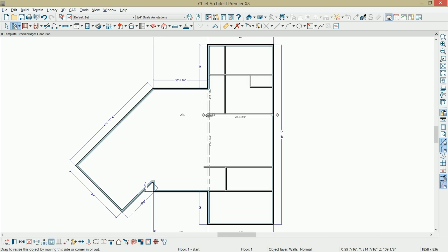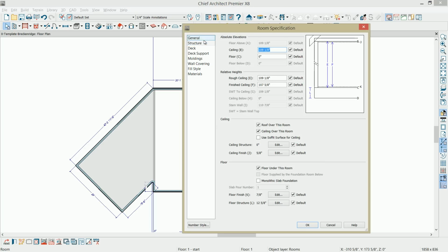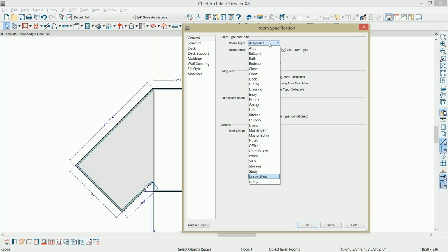And then for this wall that will form the boundary of our fireplace, I'll go ahead and pull that back out. Using that same wall, let's come over and create a room definition for our kitchen. And you know you have room definition when you click in the area and it becomes shaded, and then you can double click on that room and give it a name and a ceiling style. So in this case, let's go ahead and name this a kitchen.